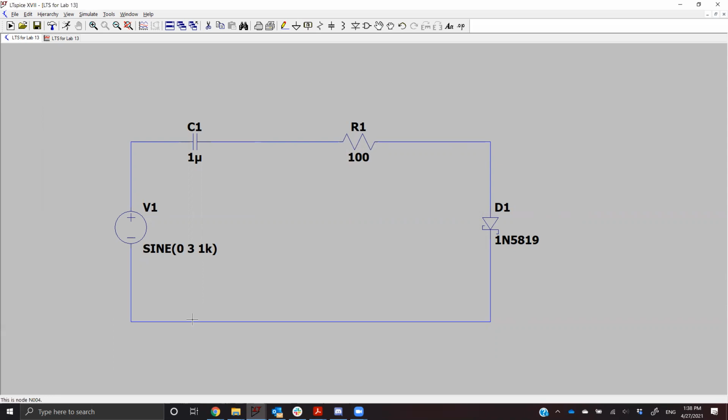Okay, so the circuit is almost complete. Sometimes in circuit schematics, you will not be shown the ground because ground is an arbitrary reference. In most cases, when building the circuits, we use the ground for the source as our reference ground, and that's most natural. But as you will find in this lab, there may be multiple references that make sense.